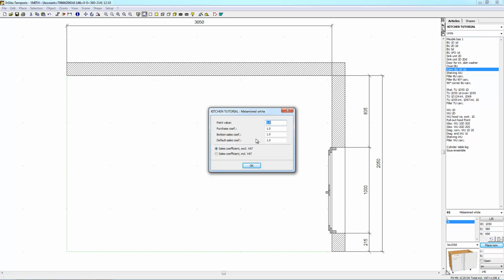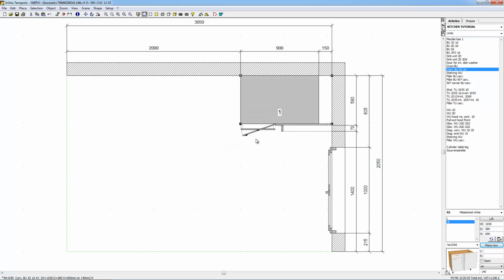If this dialog box appears, please just select OK or hit Enter on the keyboard to proceed. Please note, if KitchenDraw did not place the cabinet exactly in the corner, even though the silhouette overlapped the two walls, you should ensure that the button activating the automatic placing function, located above the vertical scroll bars, is on and not off. If you are not satisfied with the position of your cabinet, ensure that it is selected, then press the delete key to remove the article from your scene.